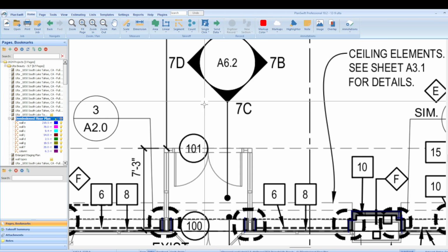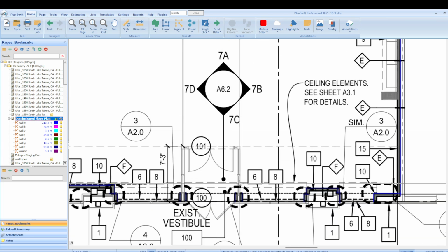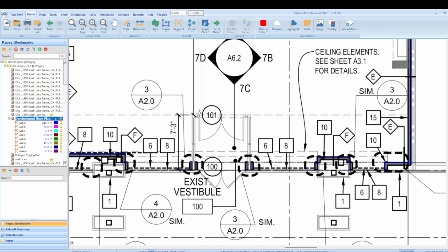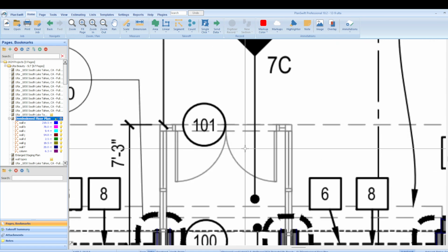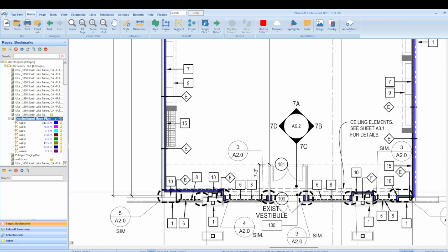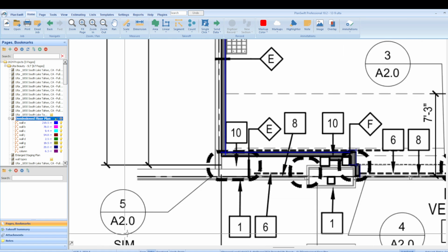This one is the same thing, but it looks like it's specific to only the door opening because of where it's pointing, and that's how we represent doors. Okay, this is a double door. It looks like wings. So this is a double door. And all of the doors have individual numbers, just like all the walls have individual marks, however they want to represent them. All the doors and windows have individual marks, and that's how we represent it. All the symbols are important.